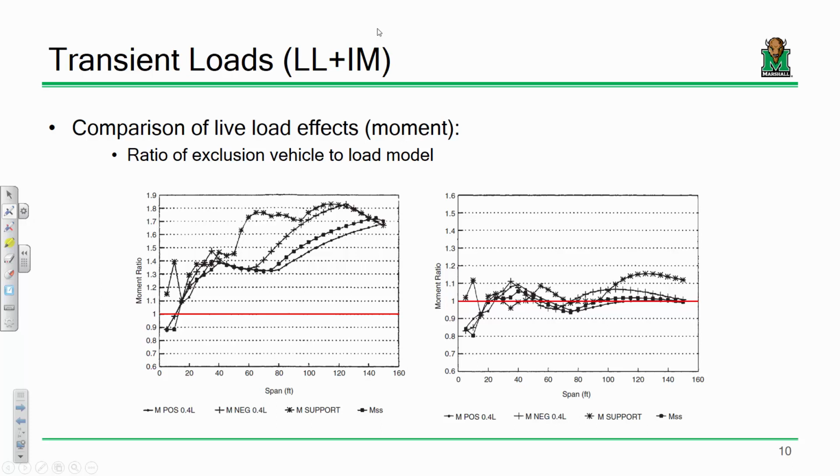So what this is plotting is what's called moment ratios. The long and short of it is this is the ratio of what the structural engineer would, and I'm quoting, guess the moments and shears are. Keep in mind, when you use the code to predict live load force effects, it is an educated guess, if you will. So what you're seeing on this axis is the ratio of what the engineer would guess versus what they actually would get.